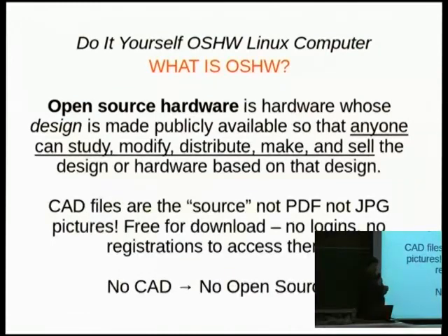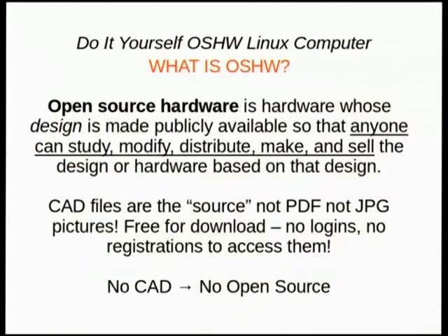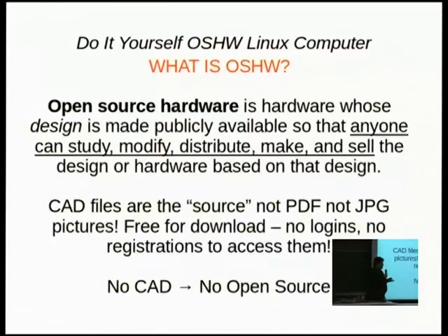To be open source hardware, a design has to come with public CAD files. The CAD files are the source. This is what you can study, modify, or reproduce. If you have, for instance, just the Gerbers, you can make the boards, but you cannot change them. If you have the schematic in PDF or JPEG format, you see the schematic, but how do you change it? You can study something from it. By analogy with free open source software, having the Gerbers and a PDF schematic is like having binary blobs. You can study from them, but it will be reverse engineering, not the native study.